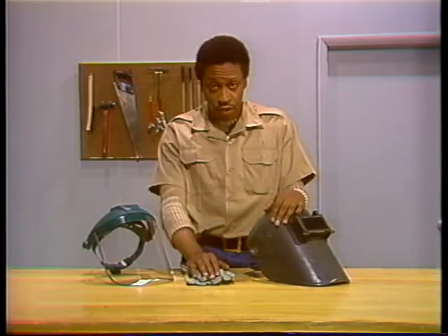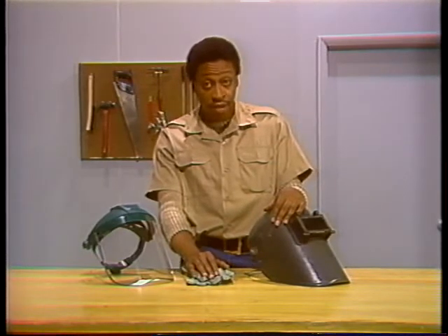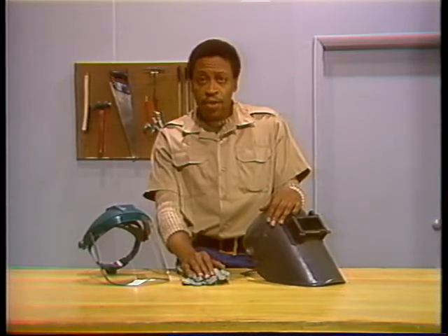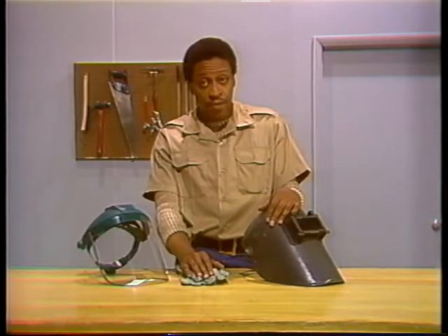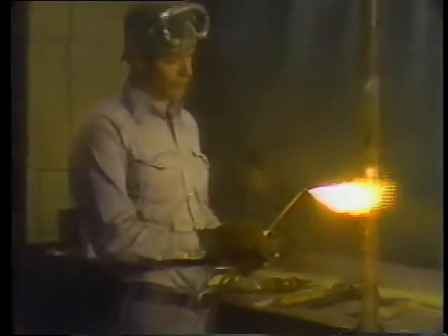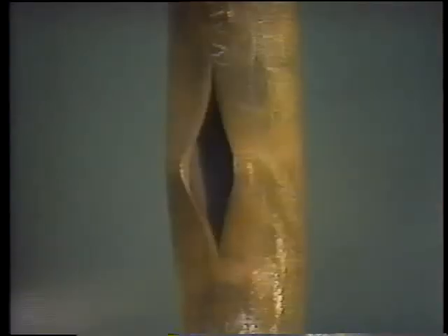We're going to demonstrate the procedure in the shop, although normally the work would be done inside the boiler. The repair steps are about the same no matter where the job is done. First, use the gas torch to heat the metal around the opening. Adjust the torch until it has a broad flame. Move the flame over the tube to heat it evenly.